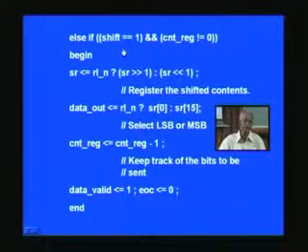And while shifting, we have to take care of right shift and left shift. We have already seen the mux implementation with a question mark here earlier, and that's precisely what we are using now. We had to take action if the select pin is RL underscore N. If it is high, it means right shift. So that's what we are doing here. Remember that for a mux, 1 input is here and 0 input is here with a colon, and of course termination of this statement. And if this is not satisfied, that is if it is left shift, it has got to be left shift by 1 bit, and that is the symbol here.